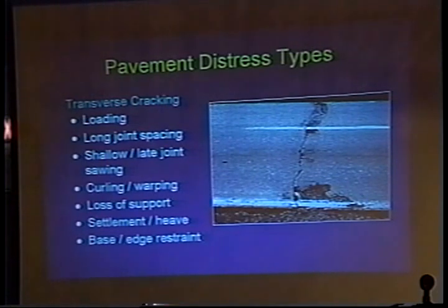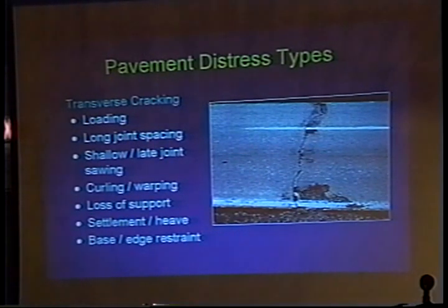Transverse cracking. A crack is going to occur where it wants to. Like I said, with the plain concrete pavements that we spec out today, you try to put joints at 15 foot. What you want to do is encourage that crack to develop at that joint. These transverse cracks that happen mid-slab can be a problem. This is the reason why we go to shorter joint spacing. Because with a 15-foot spacing on the transverse joints, we've been able to eliminate basically most of our mid-panel cracks.